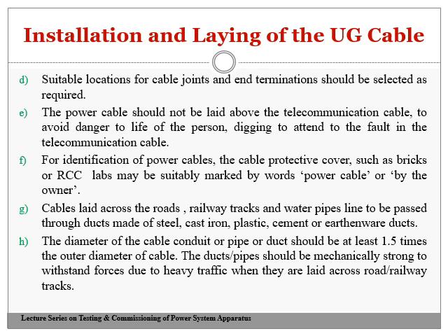It is a precautionary measure that the underground cable should not be too near to the power lines. If you dig, you may hit the UG cable directly, which may cause damage to the person operating on it.